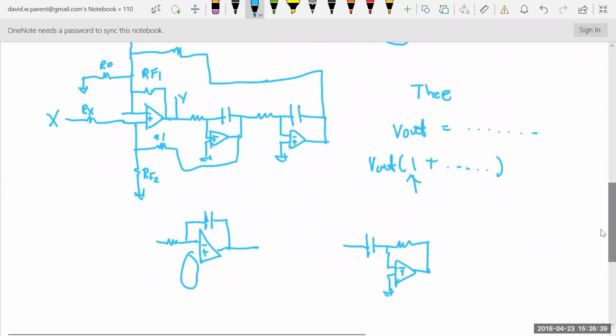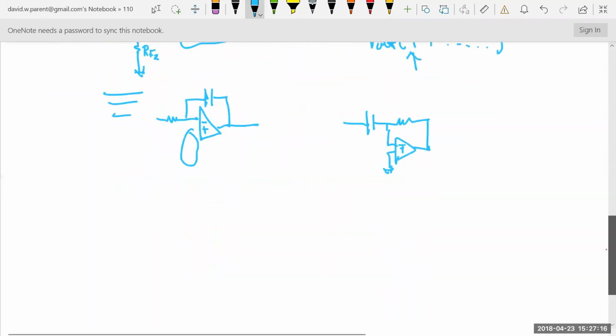All right. Now on the quiz, this was V out because it was the low pass. This node here is actually the band pass node, right? And if I take this and sum it into a summer, well, those would be the B constants and there would be the notch filter. This configuration, they actually use for a 3rd order circuit in those app notes that I showed. But if you can do this, you can do just about anything, I'd say.